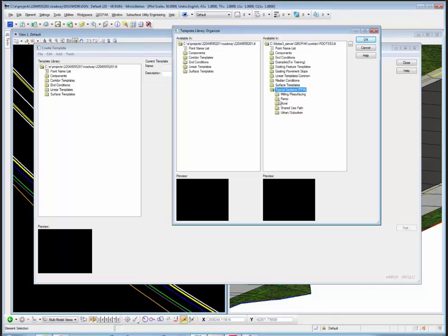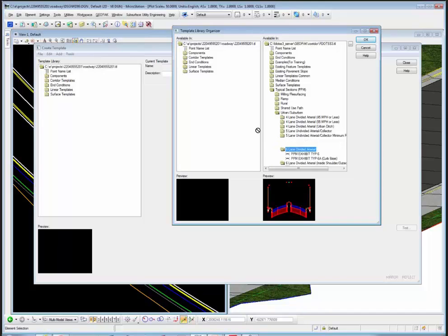So for example, maybe my project is a 6-lane divided. It follows very similar to the way the typical 20 is in the PPM, which is an urban type condition with 6 lanes. The outside lane is sloped at 3%, and there's a sidewalk that's varying. It could even be a shared use path or something up against the right of way or right against the back of curb. Whatever, it's a good example to start with. So what I would do is grab that and put it in my components folder. And now you see that I've got that same template now in my project to start with.